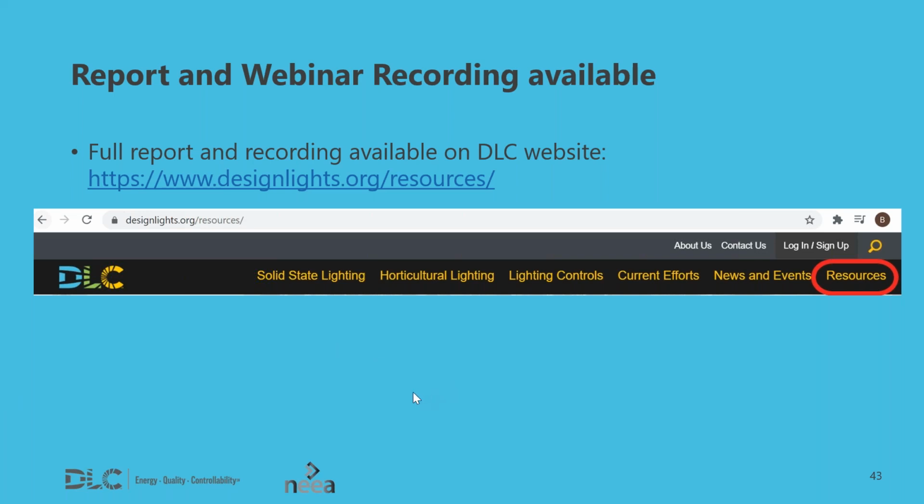Just turn it up all the way to the amount of light you are allowing the luminaires to produce. And the same concept goes to the interaction with other controls. In the same sense, when you have occupancy control, when the occupancy sensor is triggered, the light will turn on to the trimmed level instead of the full level. And same goes to daylight harvesting. When you don't have daylight, then it will stay at the trimmed level instead of the full level.